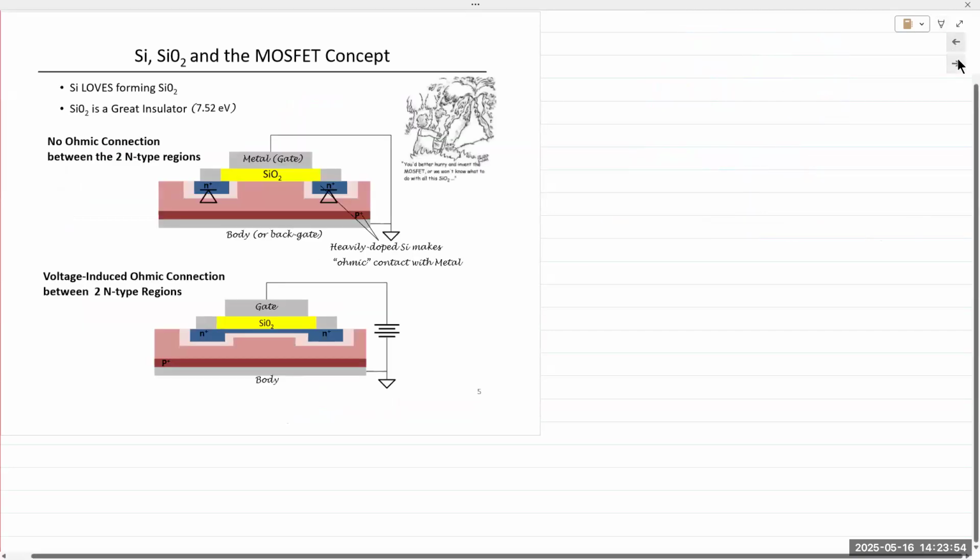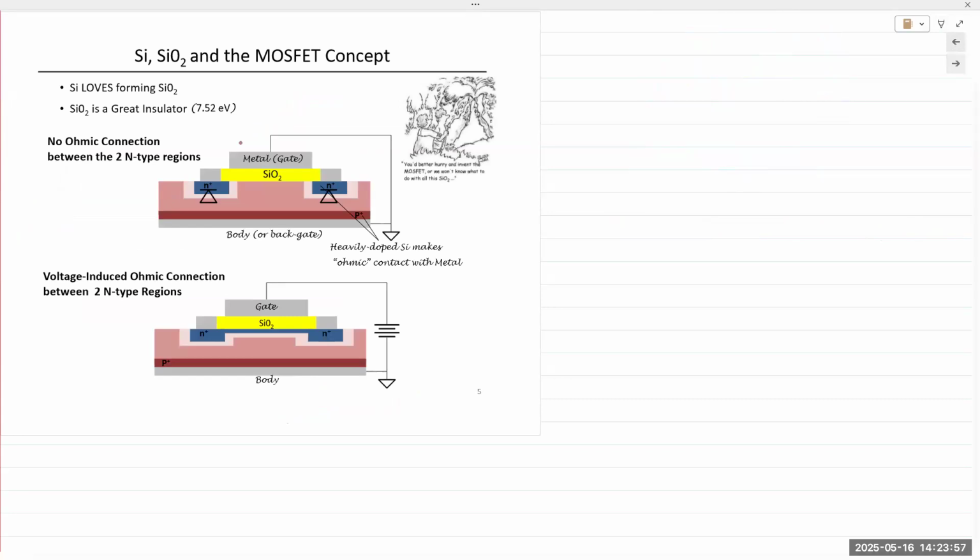Now let's get to the construction of a MOSFET. So that capacitance in the middle region was right here. Metal oxide semiconductor, MOS. Okay. Now, this is a P-type material. You have an oxide layer in the center on top. Again, this is the side view. You have an oxide material on top, and then you have some sort of metal or metallic gate on top.